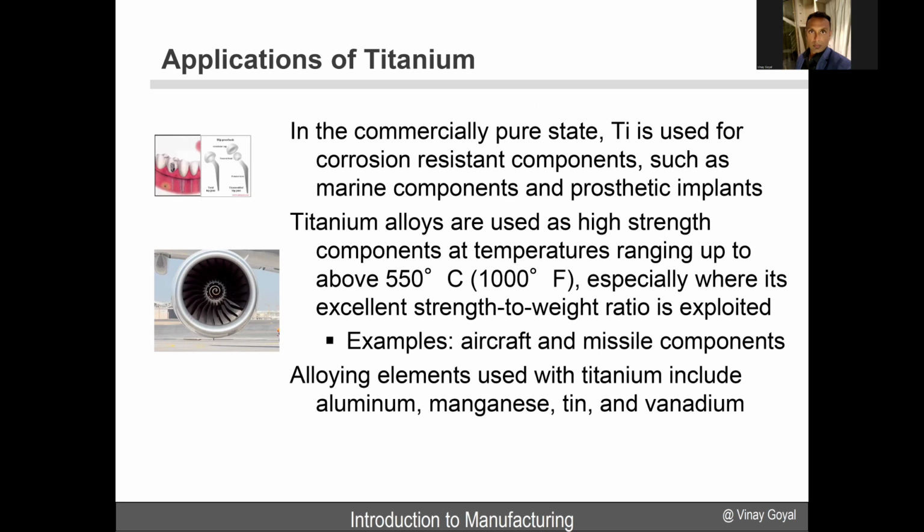It is in the commercially pure state. Titanium is used for a lot of corrosion resistant components, such as marine components and prosthetic implants. Alloying elements are also used with titanium, and that will include aluminum, manganese, tin, and vanadium.